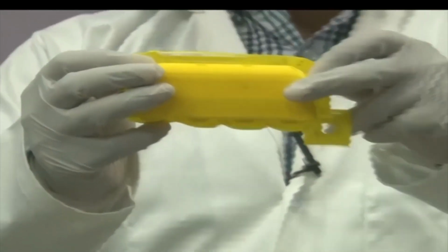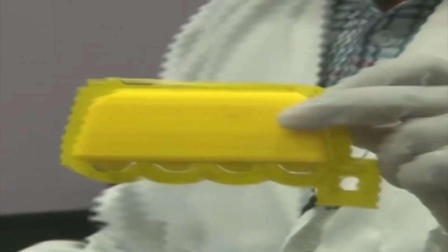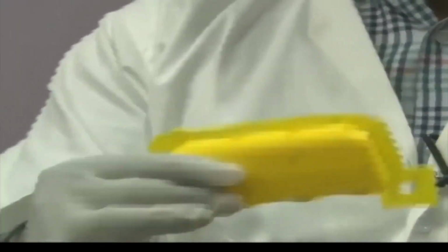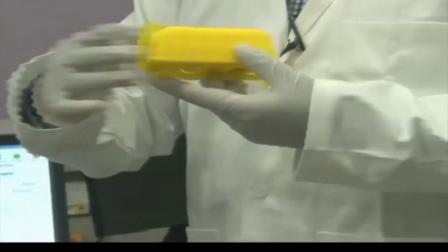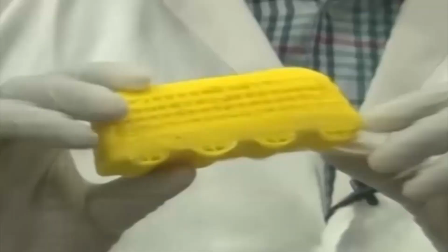So this material was produced in this way. This extra material is brim. Also we have more extra material here. Those are supports that we will show you how to remove. We can remove brim by hand very easily, manually, and we can get the finished final product. If the CAD model is flat, it's okay. If it is not flat, if it has some inclination, as I said, what would happen? How would the machine take care of the printing? It would provide some support.